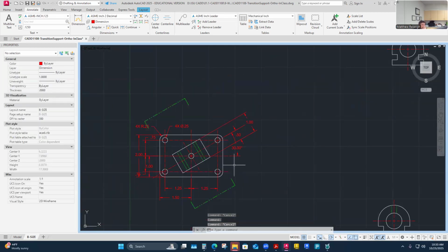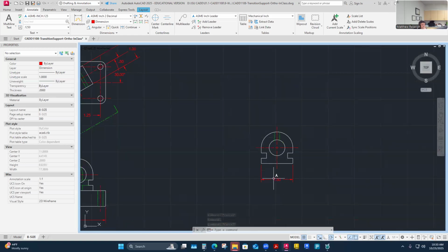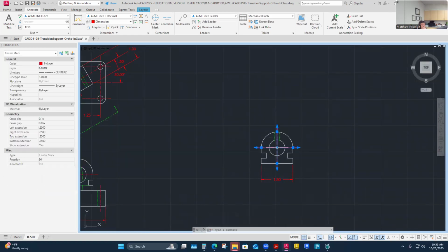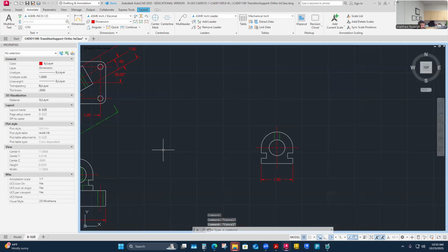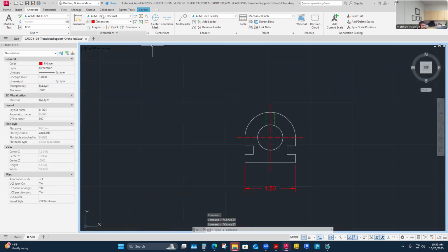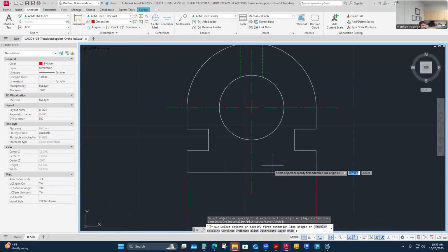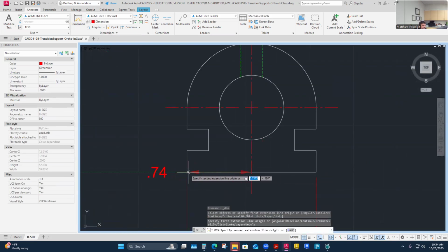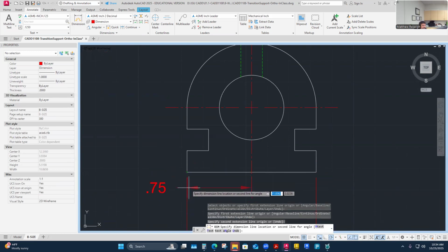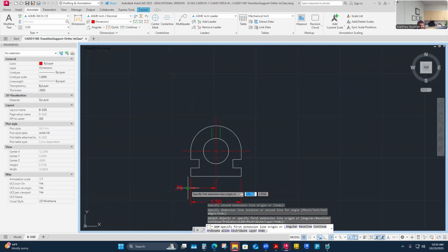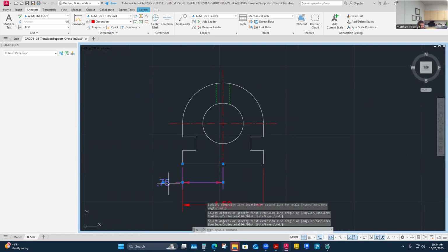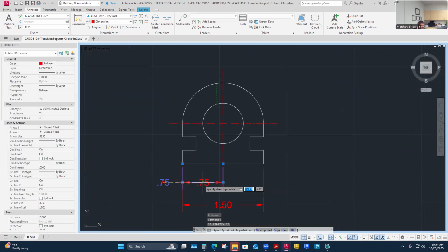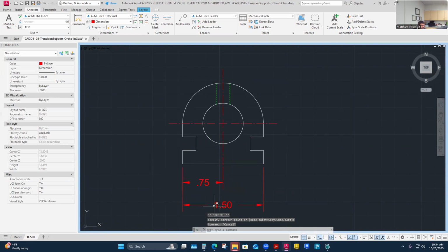I'm going to do the same thing in the other direction though. Here, this one. I want to locate this as well. So remember that these represent what's going on over there. Again, they line up with each other, even though they're on different views. They're still the same datums in some way. So I can actually establish this one pretty easily here. It's from center out here. This dimension to here is its location from a center. So it's not just a 1.5 to itself. It's actually located off center 7.5, and then its overall width is 1.5. So kind of locating that.